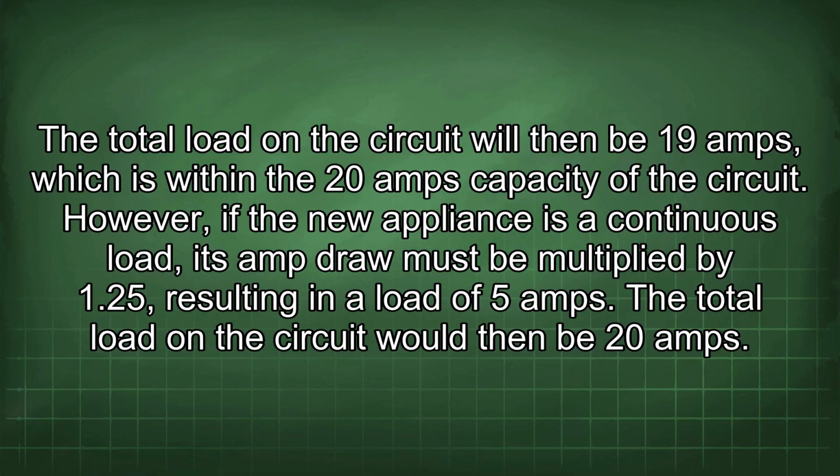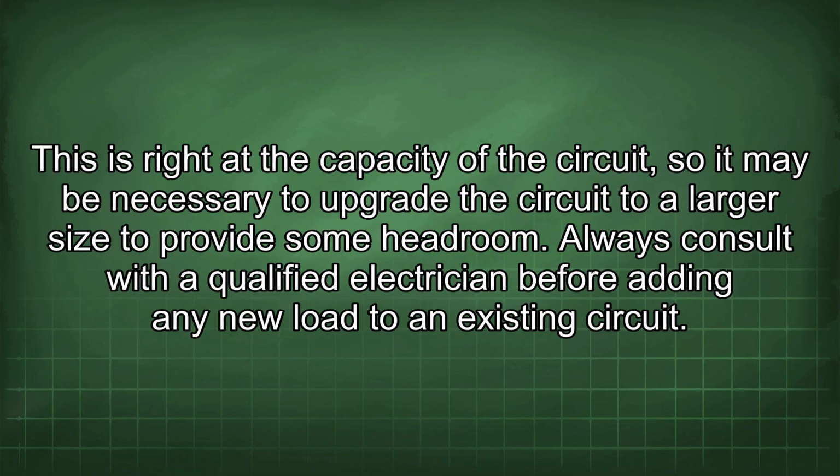The total load in the circuit would then be 20 amps. This is right at the capacity of the circuit, so it may be necessary to upgrade the circuit to a larger size to provide some headroom. Always consult with a qualified electrician before adding any new load to an existing circuit.